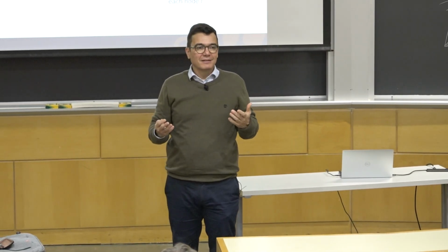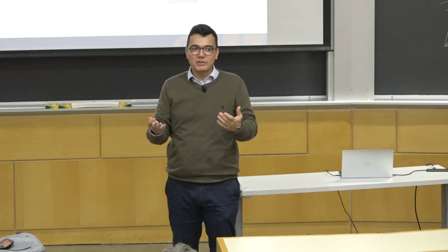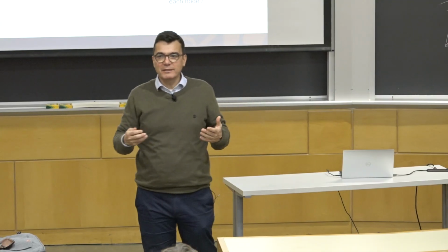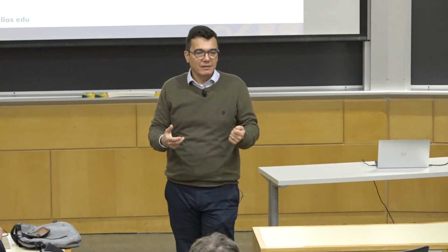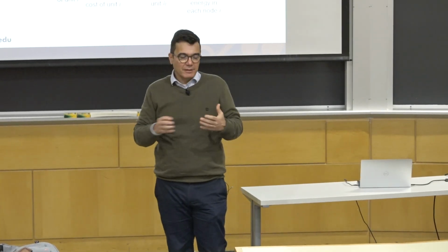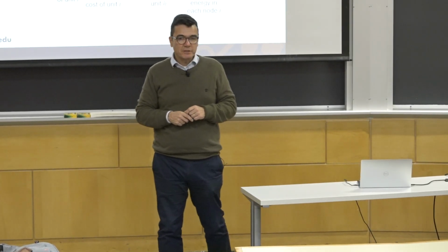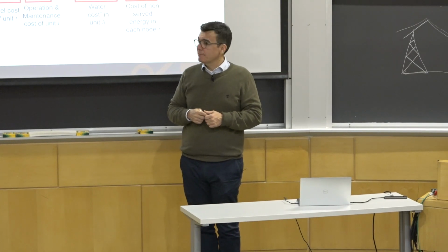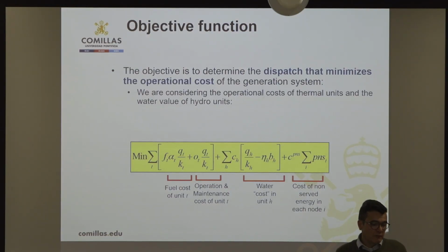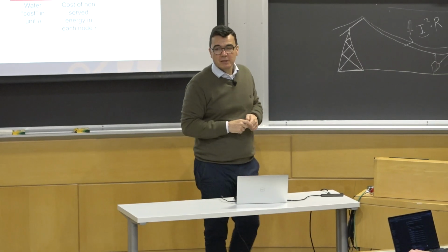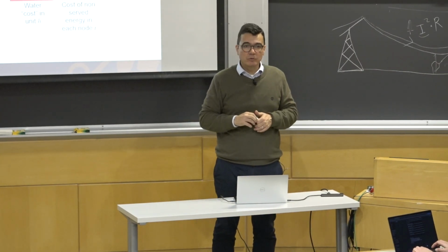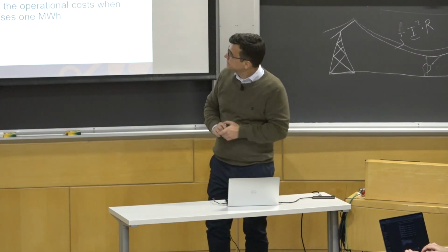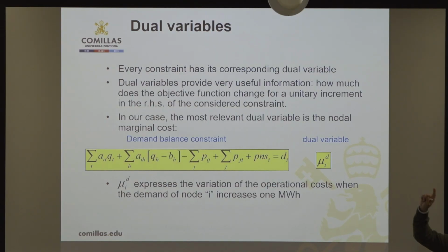Well, it depends on the usage of this electricity. If it is only for leisure, maybe it's not so problematic, but if the loads cannot be interrupted, the cost of this non-supplied energy could be higher, okay? In our case, we are going to assume, for instance, $1,000 per megawatt hour, which is a common value used in the literature. Okay. Questions up to now?